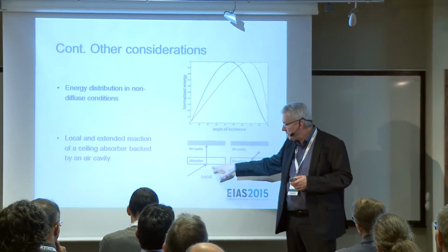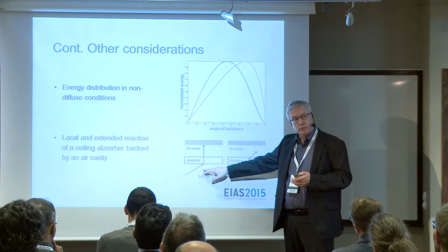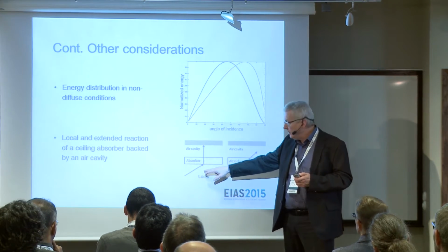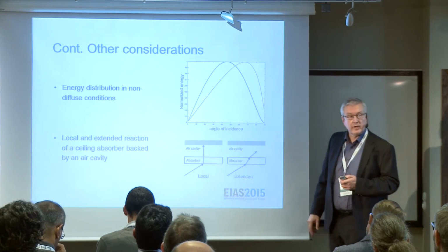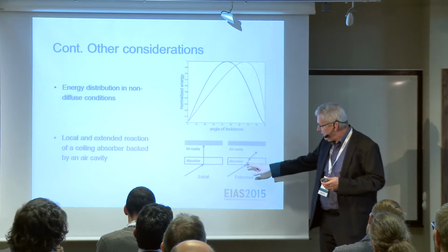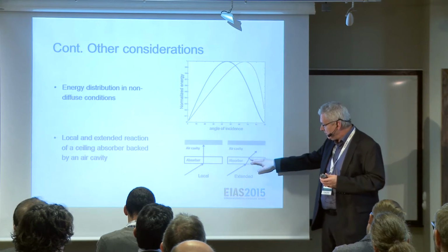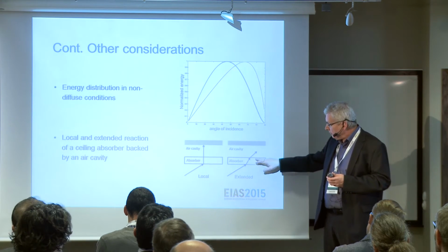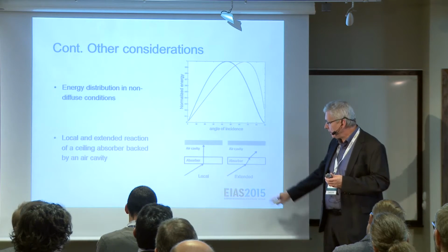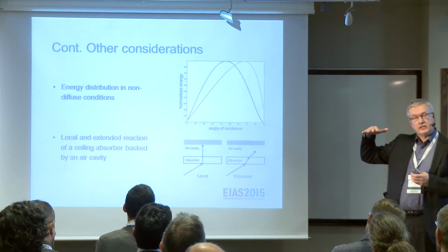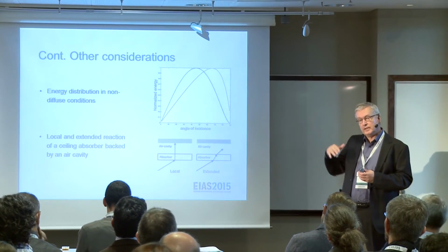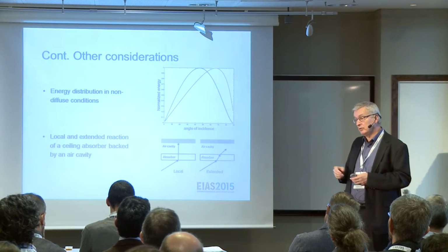As you know, normally we call a porous absorber locally reacting, meaning the sound field comes here and then the absorption goes in the normal direction. But in practice, at least at low frequencies, we see an effect of refraction. It's called extended reaction. But since we have the impedance as a description of the ceiling absorber, it's quite easy to take that into account as well.